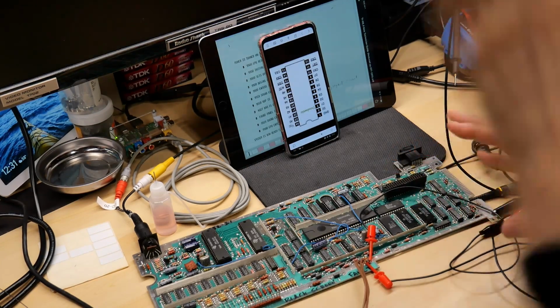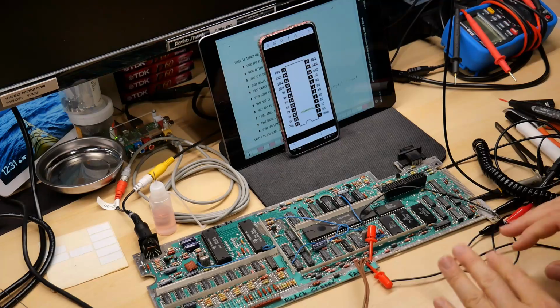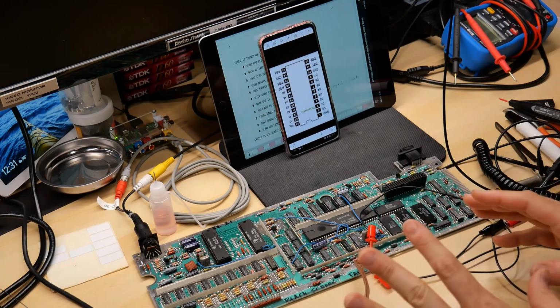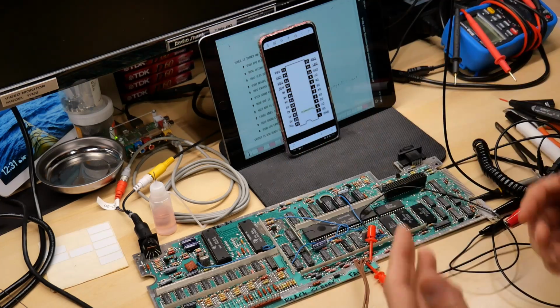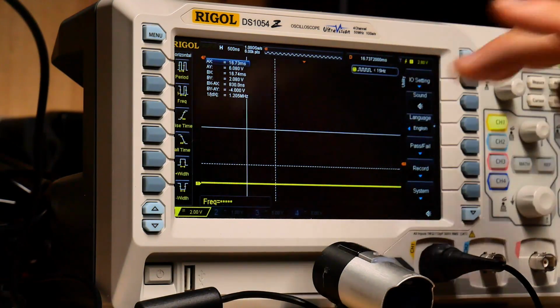So that one, everything seems to be doing stuff, although you heard the sounds this thing's making are a little weird. So I think at this point I need to look at the oscilloscope on these two RAM chips and check out these lines for ourselves visually. Okay, one camera setup.